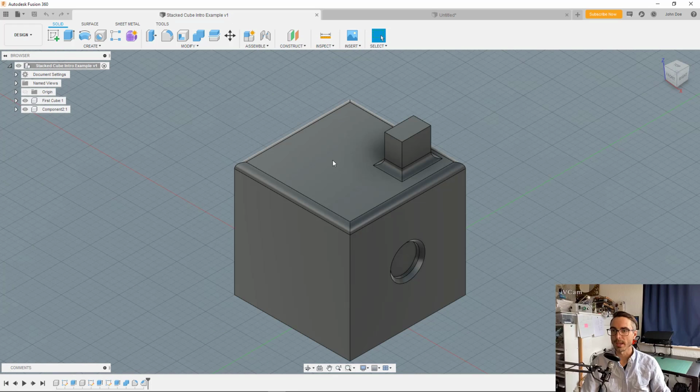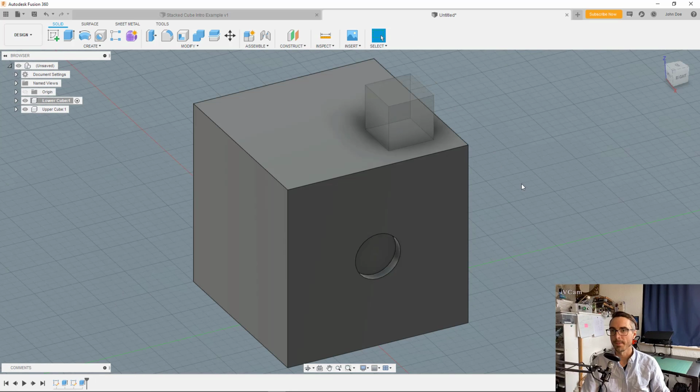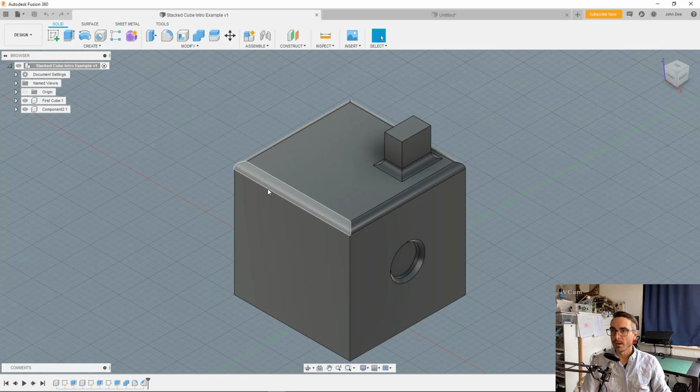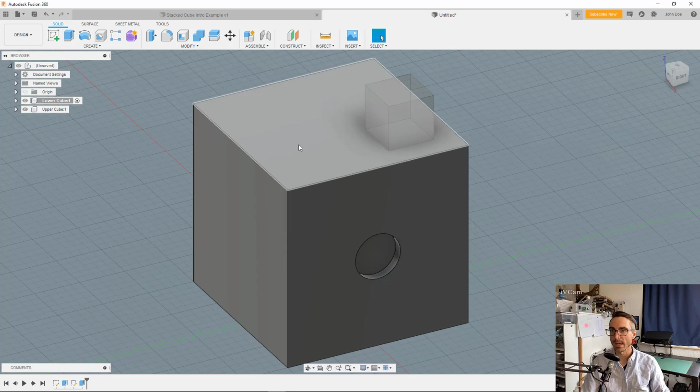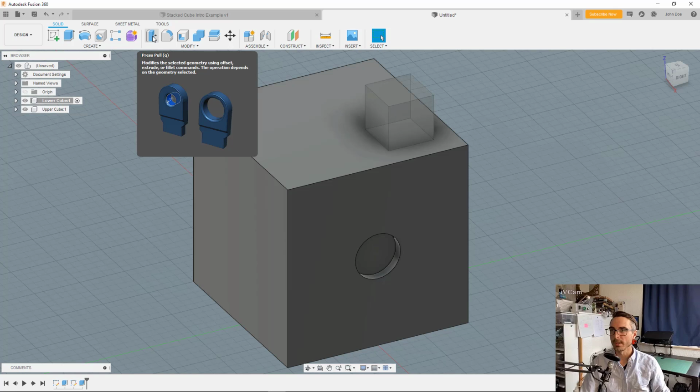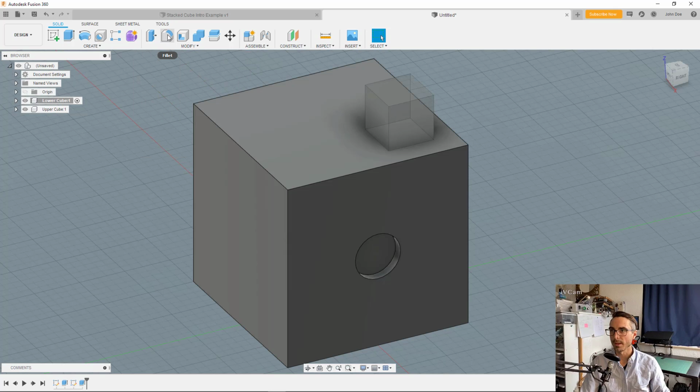Now that looks correct. We've got that pushed in shape there. As a final step here, we'll add the curves on the outside edge, the fillets, and we'll add this little cone-shaped inward scoop here called the chamfer to the face. I'm also going to show how we could combine these two objects together if we want to simplify our life a little bit. The fillet tool is up here when we're in 3D view, so I'll select it right there.